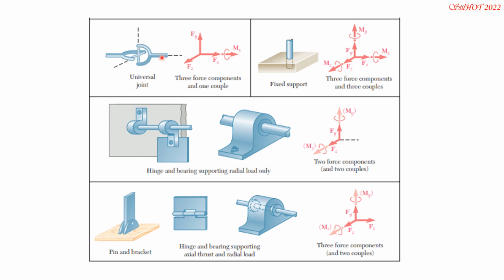for this orientation. Then if you have a fixed support, then all three forces are present and all resisting moments about the x, y, and z are also present. So three force components and three couples.